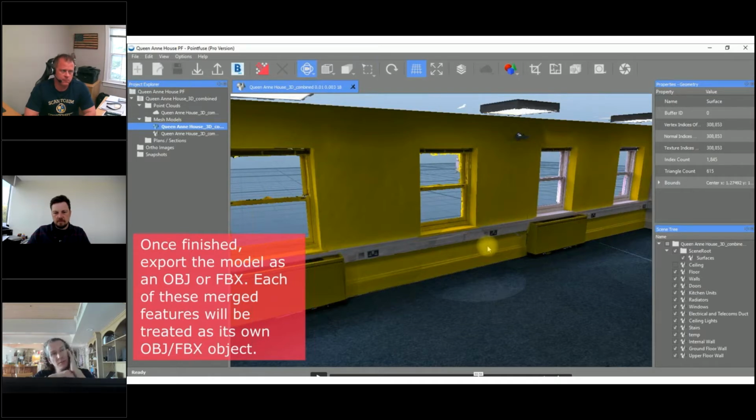Keith, do you guys do much with meshes? I think tank analysis was something that came up the other day, but we've done mesh to mesh comparison. We've also done cloud to cloud comparisons for deviation between wear points on equipment. To your point, we've actually scanned a mile from the Ohio River up to a melt shop and created a TIN surface. You have occlusions in that, and it's going to fill it in. A real quick way to make a topo.